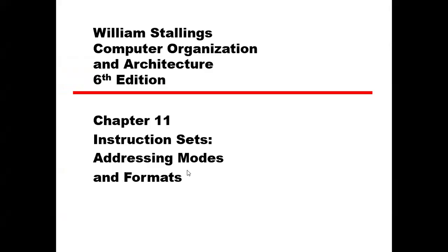Okay, now we start the session after maybe 10 minutes of this and that. We talked about instruction set, guys, as functions and characteristics. And we said, this is a recap of what we did last time. And we said that we categorize them into transfer commands, input-output commands, storage commands like load and movement, often called store and load. And what else we talked about? We needed those shift, all kinds of shift statements, shift left, shift right, arithmetic shift left, arithmetic shift right.